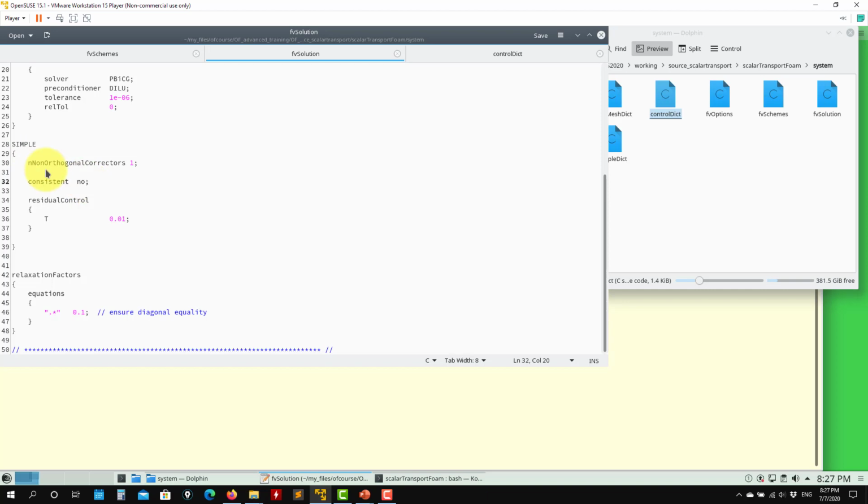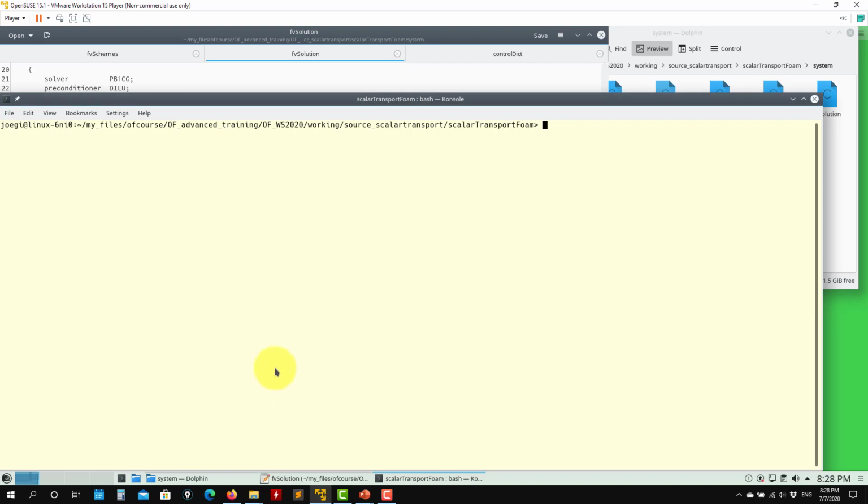And here you can change the formulation of the SIMPLE. You have SIMPLE and SIMPLEC. By any means, I recommend you to use consistent yes here. Put yes, that is more robust, and it will let you use larger under-relaxation factors. In this case, it won't be much of a difference. I will disable consistent, but if you want, you can run consistent and you won't see much difference. But when you go into fully Navier-Stokes results, there you see the difference.